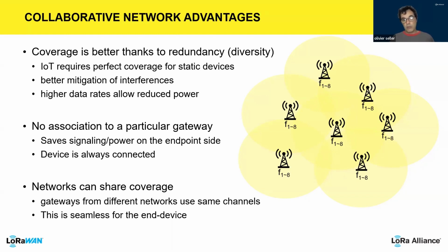When we are on the phone, we can decide to move a little bit to have better coverage, but that's not an option for a water meter, for instance. The connectivity needs to be good where the meter is. So that's good for coverage. That's also good for interference. We are using a license-exempt band, meaning that we share the spectrum with other users.